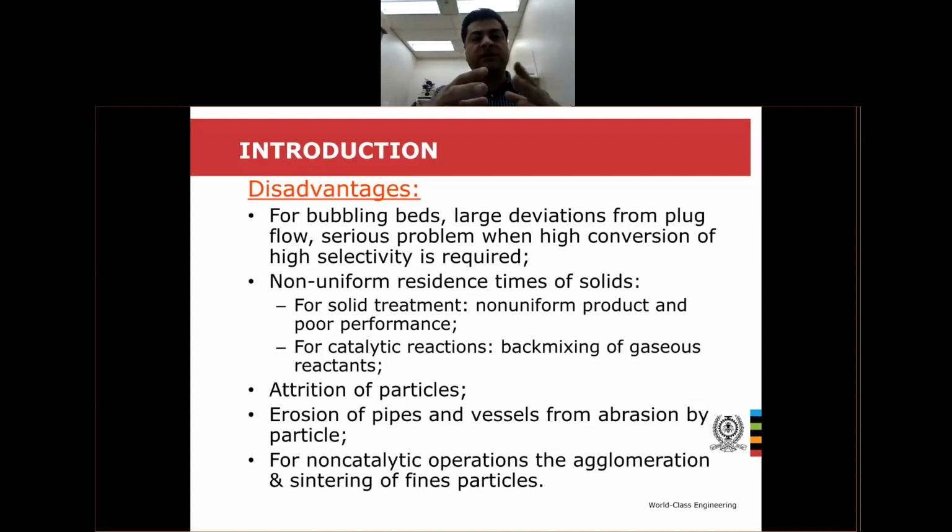So in the end, particles in a gasification reactor could stick together, and you end up with a big chunk of, let's say, a stone, and the bed is dead. It's not fluidized anymore. We call it a defluidization situation. So there could be disadvantages. But definitely, engineers who are experts in fluidization know how to manage these kinds of issues.